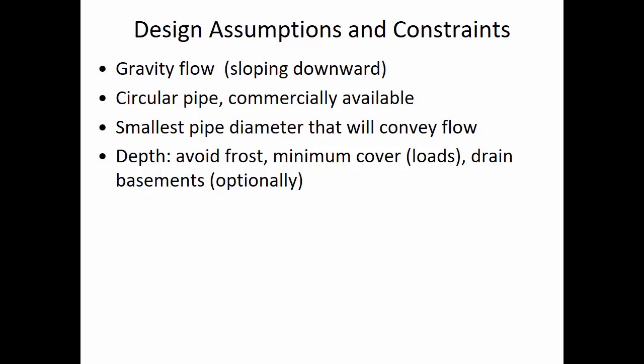The problem with having shallow flow is that there is a long wetted perimeter. And so if you have a lot of wetted perimeter relative to the cross-sectional area, then the velocity is low. So the water is going to be moving more slowly. Compared to here, the velocity is relatively higher.